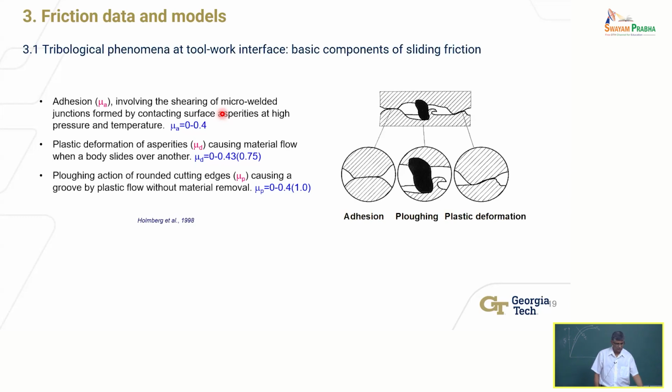Contact area of the base of this duster, you would say, right? Which is the length times the width of this duster. Well, that is really the apparent contact area. It's not the real contact area. Why? Because neither of these two surfaces is perfectly flat or smooth, right? If you look at it carefully at high magnification, there are these peaks and valleys. So the real contact area is the contact between these opposing peaks and valleys, right?